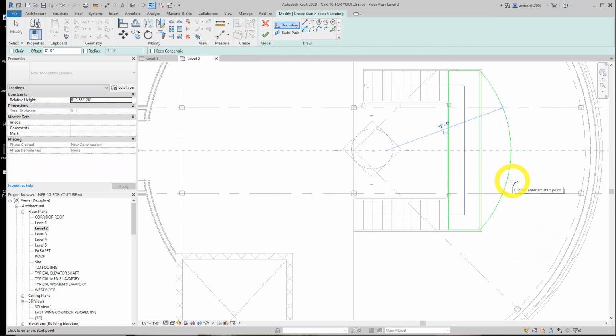And in this case, we gotta end our sketch mode as always, checking if we have any gaps, overlaps, or duplicate sketch lines. And there's one little step here they don't exactly say perfectly. We're gonna go and hit escape twice. We're back to the selector, modify here. That's what happens when we hit escape twice, right?